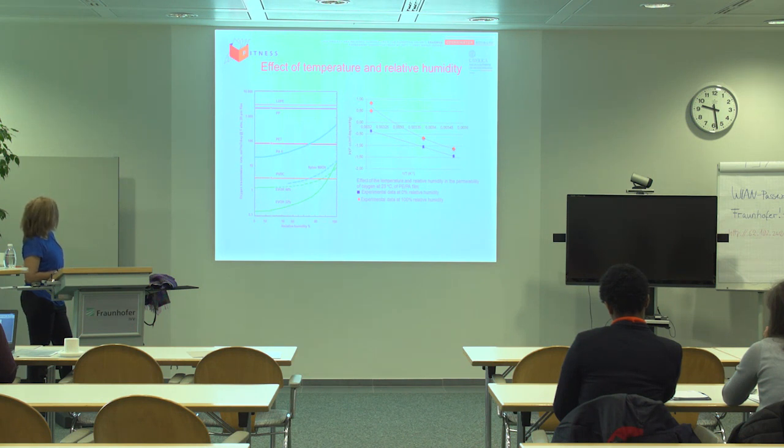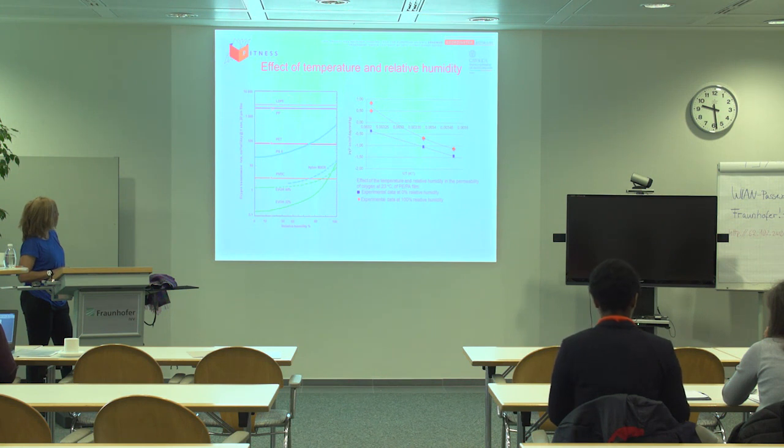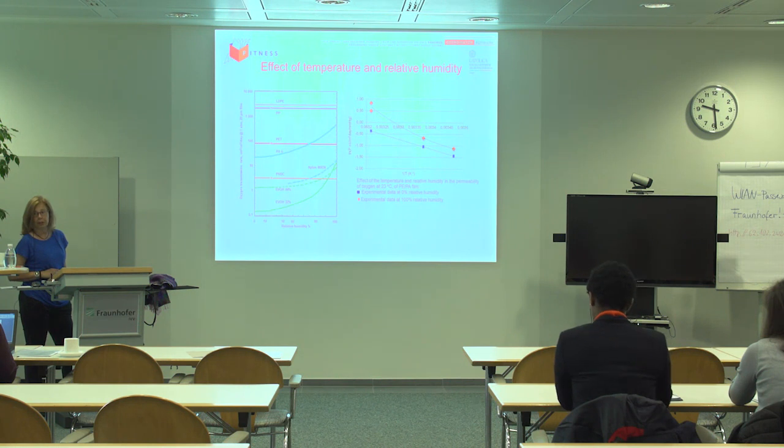Now we are focusing only on oxygen barrier, and we see that for the polyolefins like low density polyethylene and polypropylene, and also for PET and also for PVDC, polyethylene has a very high permeability, but it does not depend on the relative humidity.